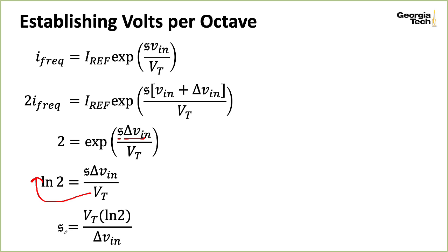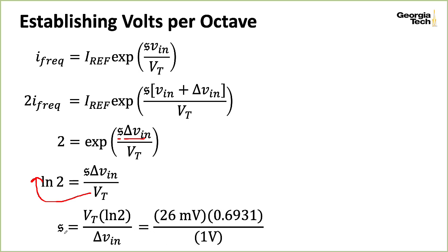All right, so plugging in some numbers here, let's suppose for a second we're operating at room temperature, 298 degrees Kelvin or 25 degrees Celsius, which I think is 77 degrees Fahrenheit, which is actually a bit warm for me. So let's take 26 millivolts here for VT. We'll deal with the change in temperature of the thermal voltage later on in the lecture. Right now we're just dealing with canceling out that saturation current, that I sub S. Okay, so logarithm of 2 is like 0.6931.